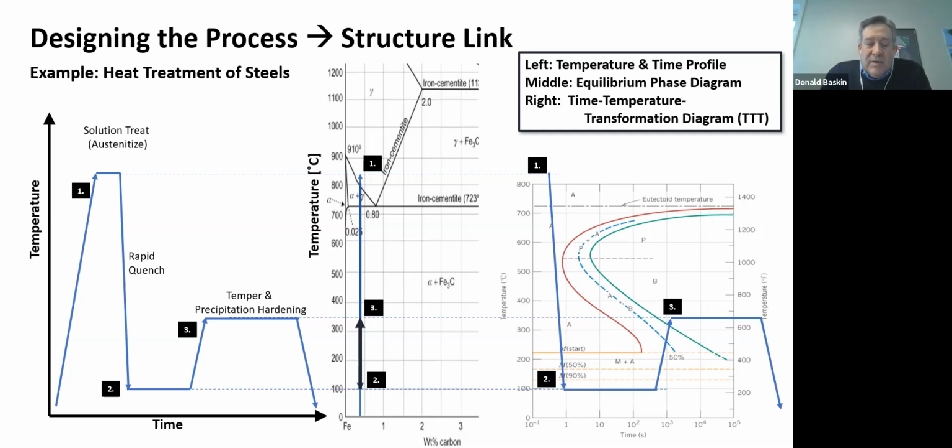In certain alloys of steel, where you have a lot of alloy content, you can also precipitation harden the material. So in addition to having the martensite, you can also have precipitates in there, like combinations of metal and carbon called metal carbides. An M2C carbide, for example, is a very potent strengthener of steels.